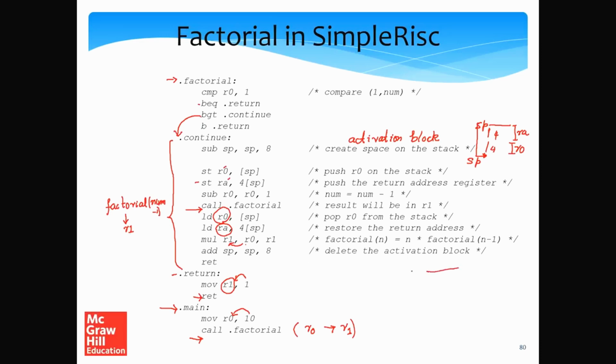So think about this. At the beginning of the function, the stack pointer was here. We needed to save 2 local variables. We need to spill 2 registers actually. So the new stack pointer pointed here. Once the function was over, we restored the value of the stack pointer to again point to where it was originally pointing. After this, since the value is in R1, we return back.